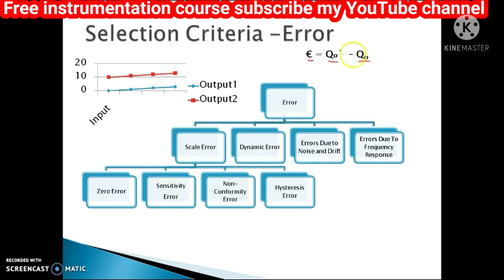Let's look at how the errors are divided into different types. The scale error, dynamic error, errors due to noise and drift, and errors due to the frequency response of the transducer. Let's start with the scale error. Under that we have zero error, sensitivity error, and the non-conformity error with hysteresis error. Let's look at zero error. Zero error is the error with a constant factor, given with this example of a graph.